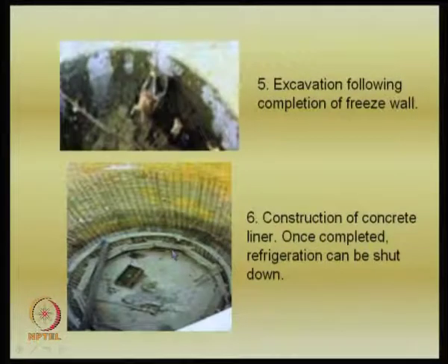Is it not? Excavation following the completion of the freeze wall. Suppose the area is totally frozen, then you can start excavating, because it will not collapse. Once after that you make the permanent wall constructed, and once that permanent thing is constructed, refrigeration can be shut down. That is it, as simple as that. It is a very temporary solution to some of the important issues.